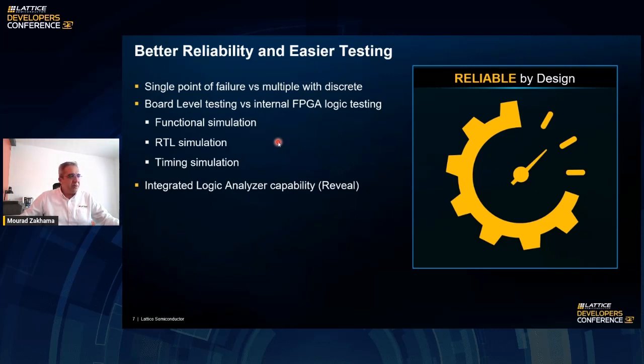There's also the possibility of having a logic analyzer. There's an integrated logic analyzer capability within the device. It's called Reveal. And Reveal allows you to probe internal nodes in the device and display them on the screen and debug your design as you go through the development.